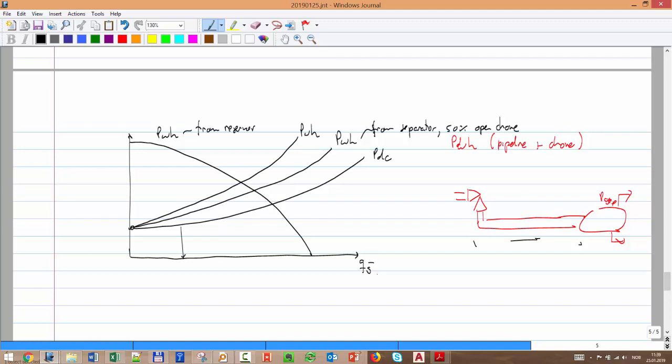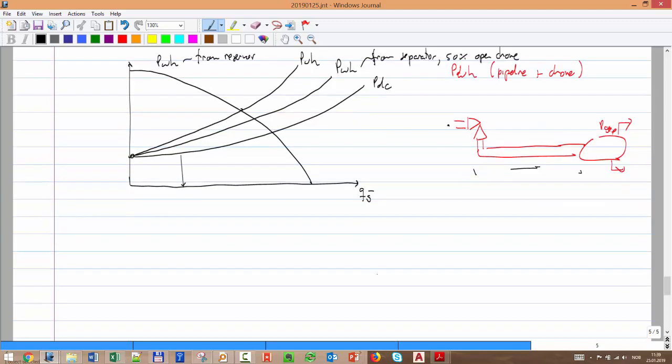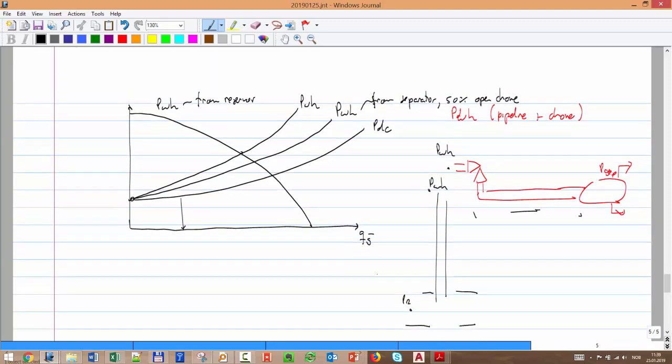And at the same time, we have the same issue, right? Both of them are looking at the same place. That's P wellhead, and here I have a pipe, the tubing, and I have my formation here. And I have P wellhead. They're actually in the same place. Therefore, the only feasible solution, if I put this system together, that's the only rate that I'm going to get for fully open choke.